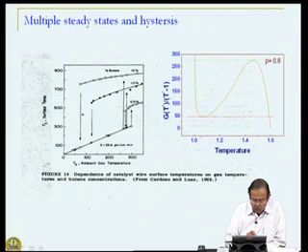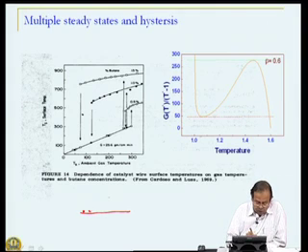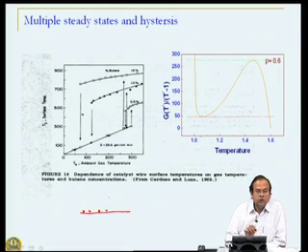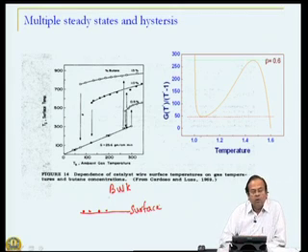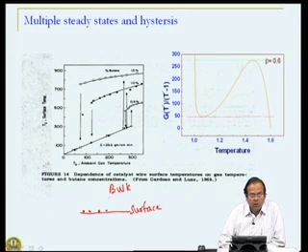What is happening in this particular reaction is butane dehydrogenation to butene over a catalyst, and this catalyst is now a wire catalyst, a thin wire, and the catalytic elements are only on the surface of this wire. So, there is no diffusion to speak of. What is important here is you have bulk and then you have surface, and the entire reaction is on the surface. So, there are only external resistances in this particular case.